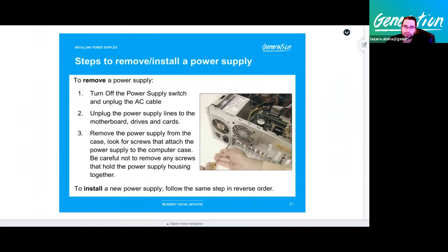So let's say you have a graphic card as an example. Your graphic card only accepts 6 pins. If you only had an 8 pin and you cannot separate 2 pins, then you can't use it because it won't fit in correctly. So by having that little tab where they can separate it, you can convert an 8 into a 6 pin. Think of it like that.